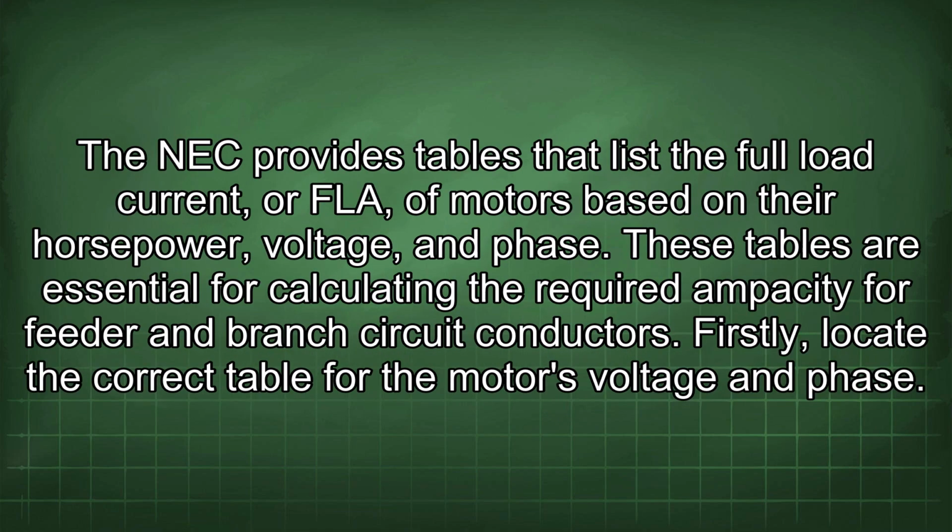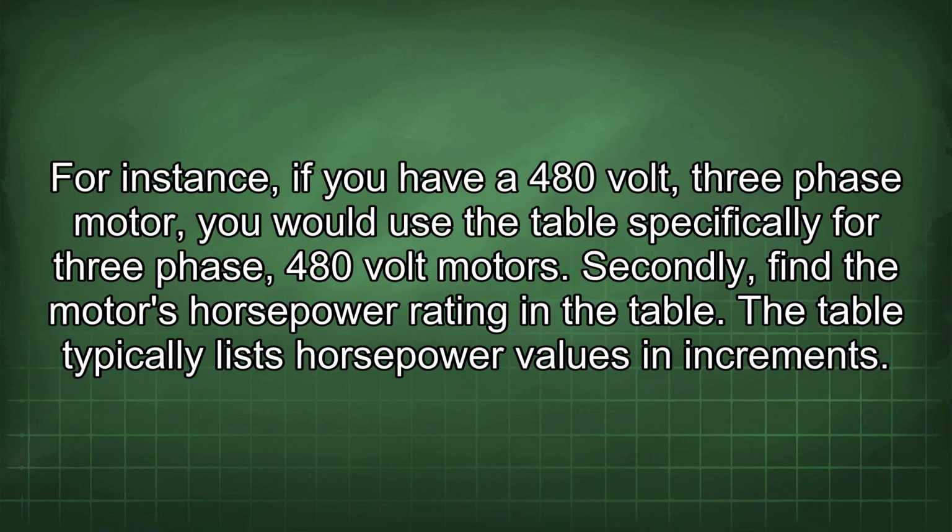The NEC provides tables that list the full load current, or FLA, of motors based on their horsepower, voltage, and phase. These tables are essential for calculating the required ampacity for feeder and branch circuit conductors. Firstly, locate the correct table for the motor's voltage and phase. For instance, if you have a 480 volt, 3-phase motor, you would use the table specifically for 3-phase, 480 volt